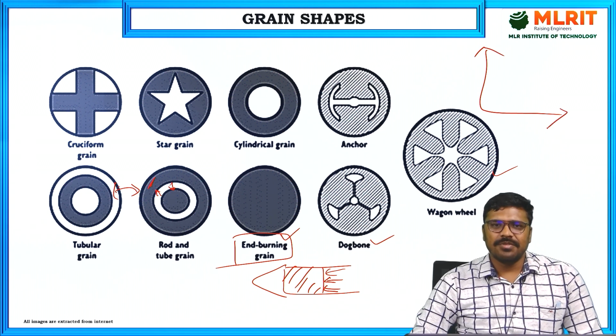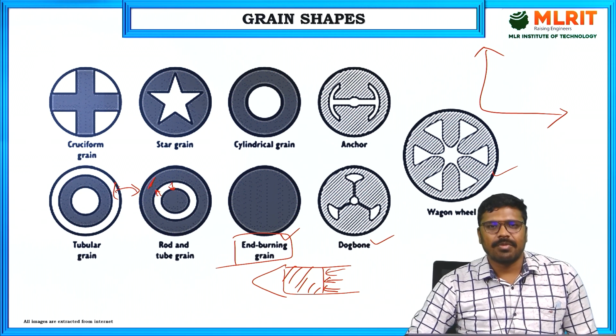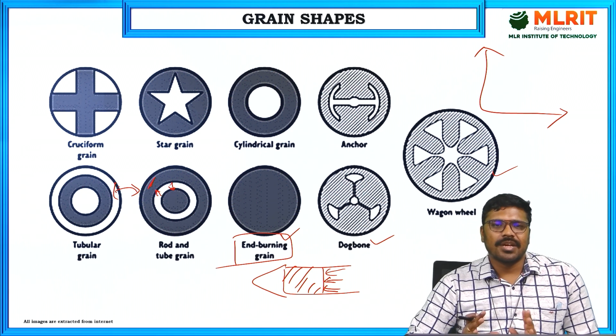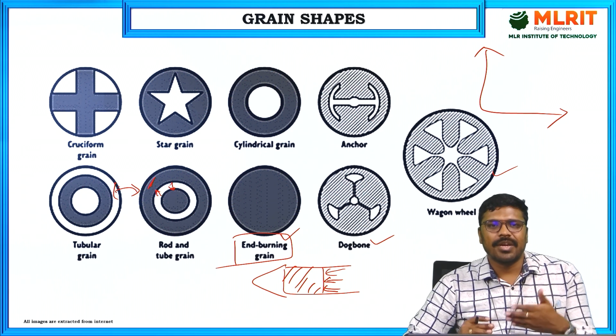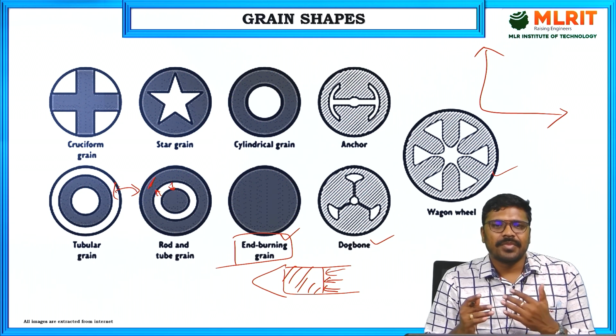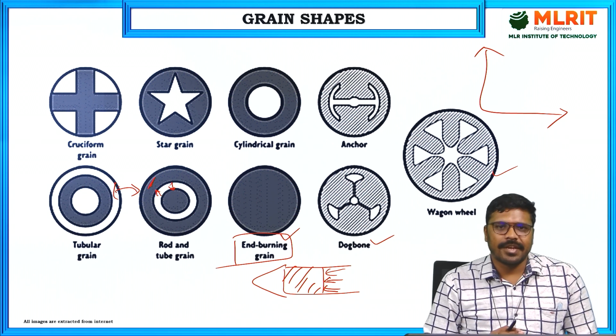See, the difference between a solid propellant rocket motor and a liquid propellant one is that the solid propellant rocket motor thrust profile cannot be changed immediately like a liquid propellant rocket. In a liquid propellant rocket motor, we can control the valves and fuel flow rate, and we can increase and decrease the thrust as we wish. But coming to solid propellant grains, depending upon the thrust profile, you have to design the propellant grain shape.